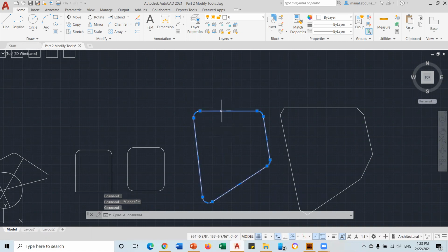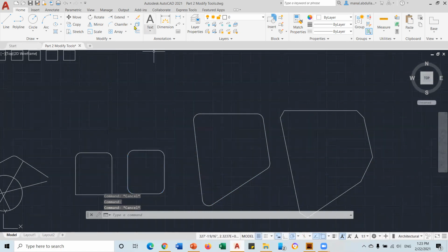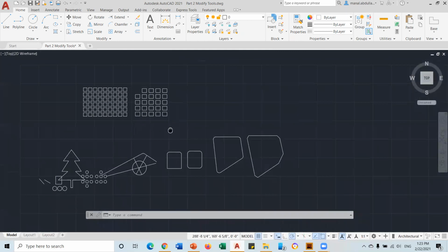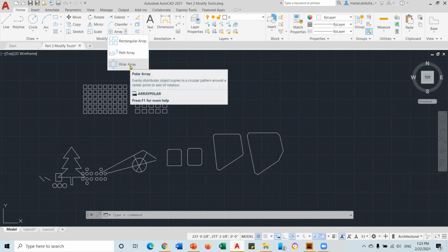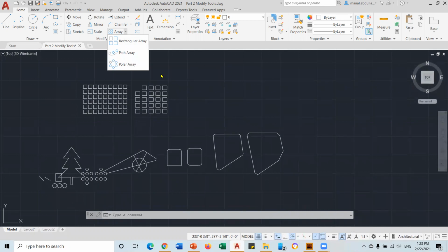Let's say here we have this polygon or this polygon, we can explode it. X enter or explode. Okay. So this one, it's all segments. So we can explode, click on it, enter. Now it is parts. Okay, so the explode command will explode any polygon or any associative array. Now we need to talk about the polar array. Also, I recommend watching the videos in the description for more exercises about polar array.